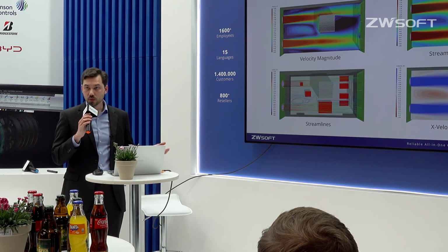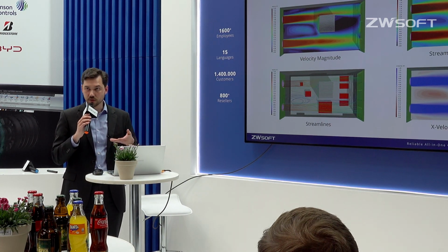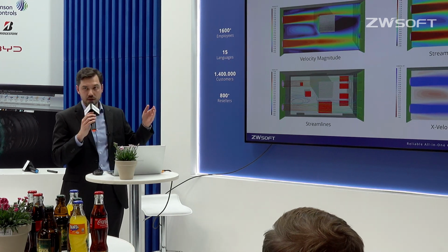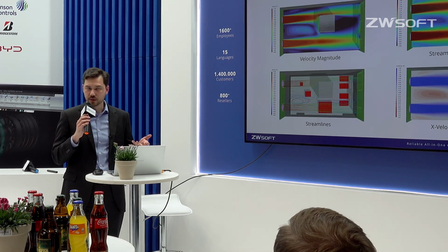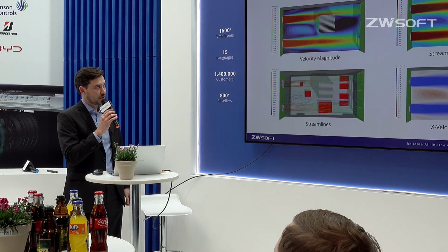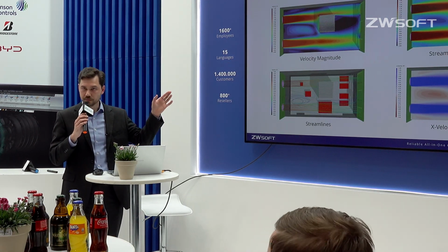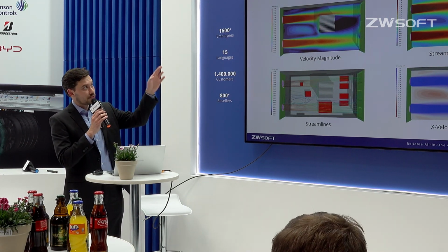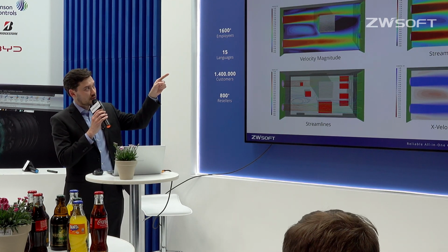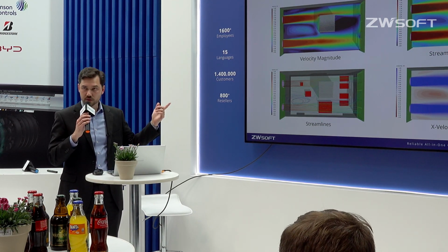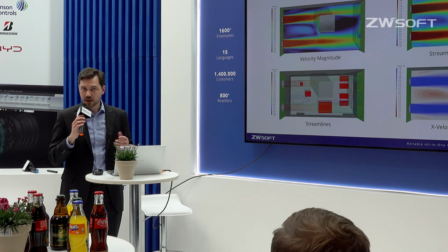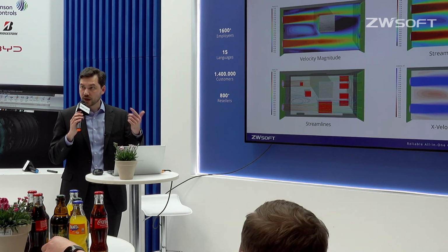And that's not what we would like to find behind the heatsink. Behind the heatsink, we would like to see velocity traveling from left to right, carrying the temperature from the heatsink out of the simulation. So this spells a problem. Furthermore, in front of the heatsink, there is a light blue region surrounded by a zero velocity region. This often implies a switch in velocity's direction.